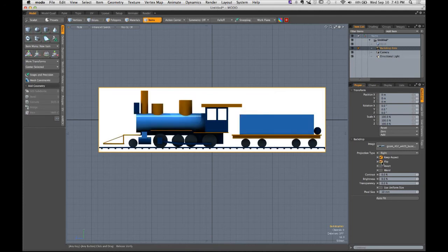Now, it's facing the right way. It's in your backdrop item properties: Flip. You very rarely, only in certain situations, truly need to rotate backdrop items. Changing the projection type and flipping the image often aligns the image to the grid the way we want it to go. Just rotate on the y-axis?